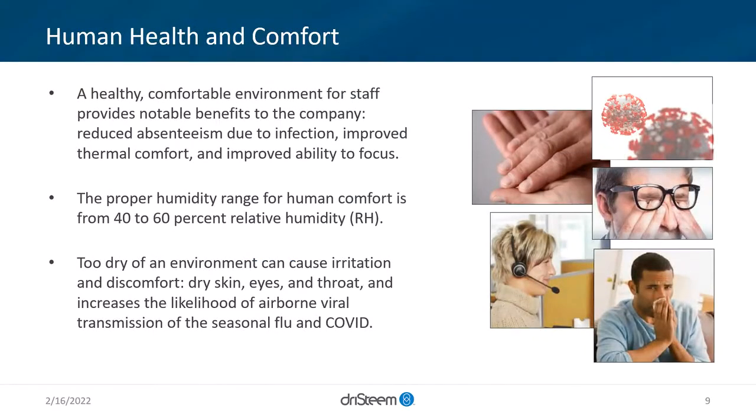And lastly, these aren't factories and facilities and clean rooms without human occupants. So having a comfortable and healthy environment is something that can really help or hurt the bottom line, with dry, cracked skin, eye irritants, or even influenza or other viruses. Going back to the Sterling chart, that could be propagated by ranges outside of 40 to 60% RH.